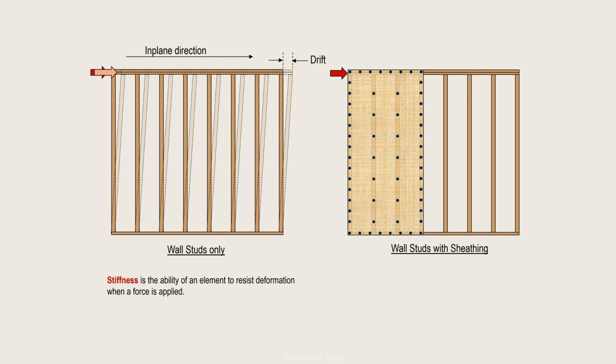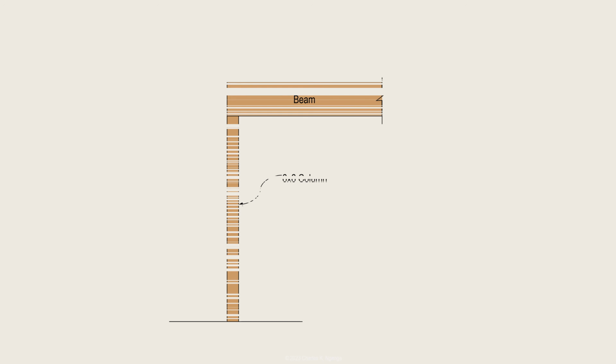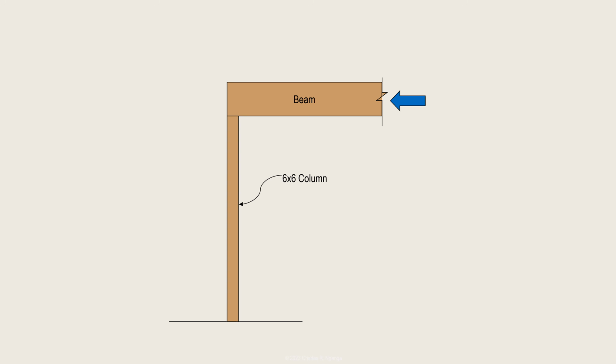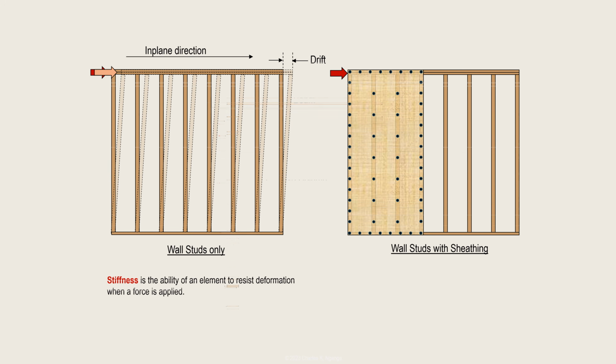Large deflections cause damage to framing elements and wall finishes and may lead to building collapse. If a column or bearing wall carrying vertical loads leans on one side due to lateral loads, its capacity to support the vertical loads is compromised, and this may result in catastrophic consequences. To prevent this, the Residential Code requires and specifies bracing methods and minimum bracing amounts that will provide the necessary stiffness and strength to resist lateral loads at the appropriate hazard level.